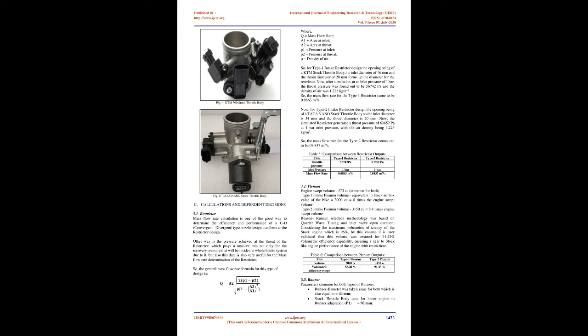software Ricardo Wave. After this, different shapes had to be considered, and each shape was iterated and simulated for both packaging and flow characteristics in SolidWorks assembly and SimScale CFD respectively, to reach a point where both parameters are considerable. Finally, this was used to optimize the ECU fuel as per the fuel characteristics of the plenum chamber to find a good balance and desired performance output.